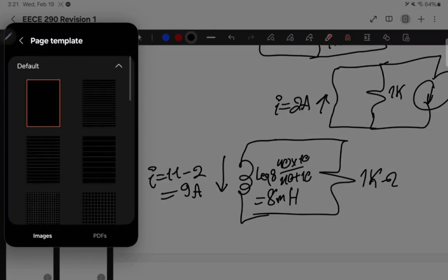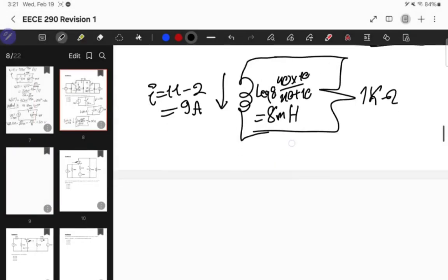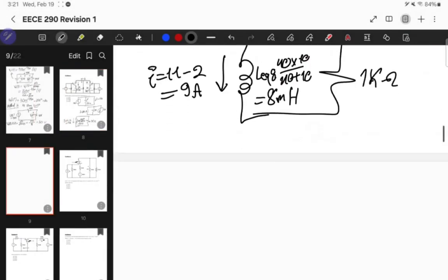So what I can do is get the current in the L equivalent, because I know that the current is continuous. So whatever I get for I0 minus is equal to I0 plus. So the expression of I, I'm gonna call it I equivalent of t, is equal to 9, which is the initial current in the equivalent inductor, times exponential minus, now I need tau.